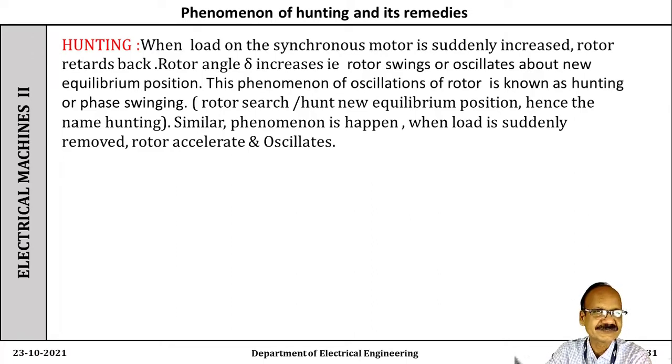In this video lecture, we are going to learn what is hunting of the synchronous motor and what are its remedial measures. Now, when the synchronous motor is loaded, the rotor falls back and an angle is generated between the stator polar axis and the rotor polar axis, and it is known as load angle or torque angle or power angle.